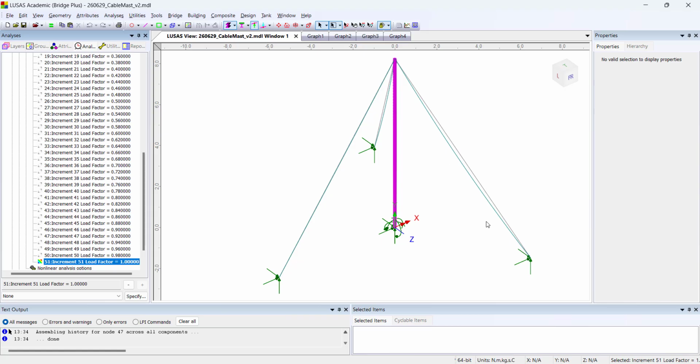As the wind acts on the mast, the pretension in these cables decreases, causing them to become progressively more flexible. The third cable, the critical cable, behaves differently. Its pretension increases, causing its shape to move closer to the initial straight chord defined by its endpoints. This is, of course, as expected.